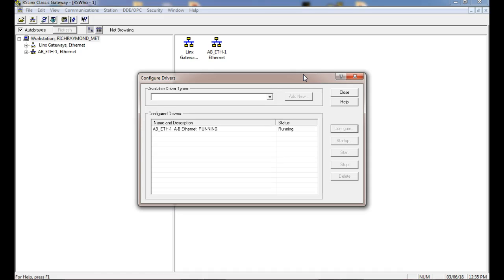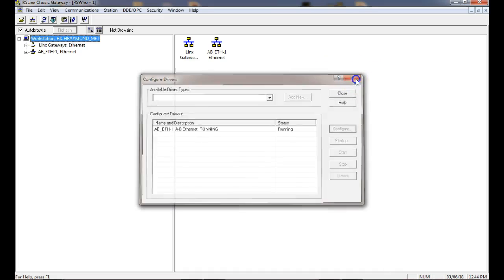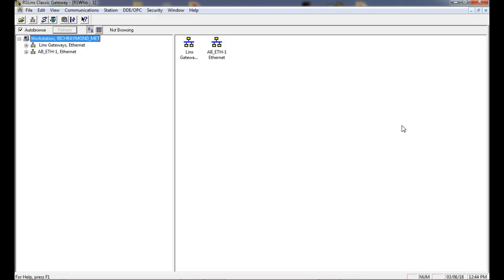So the more we advance, the less the user has to know. But the first thing you do when you put a new PLC there is establish what? The communication. And then I create a program. What's the first thing I do when I create a program? Select the processor that we're using, right? If it's a modular PLC, then we have to add the size of the rack and what modules are in each one. If it's a hybrid PLC and I slap another module on there, we're going to have to configure the communication with that other module, right? You understand? So it'll be very simple. So when we come over here and look, so let's